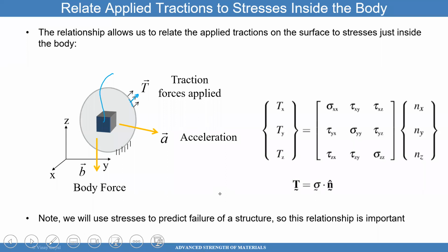I showed you how stresses can be related to a slanted surface, and how principal stresses can be calculated on an arbitrary slanted surface, how to find that slanted surface, and what principal stress corresponds to it. That's very useful in the design of brittle materials and other materials of interest.